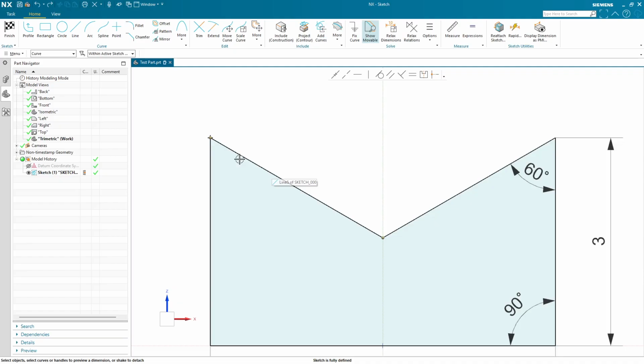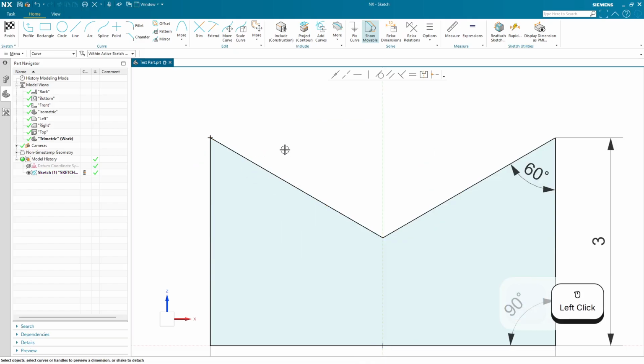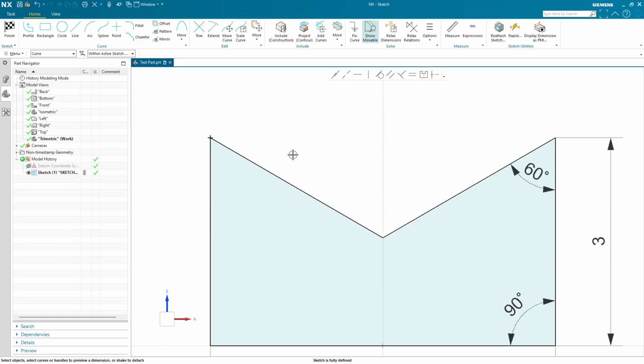So you might be asking, how do I deselect? You might have drawn stuff already or clicked on something and you're confused and maybe hitting escape to get out of there. To deselect things in NX, you hold shift, and as you hold shift, you click the thing that's selected and it deselects. If you've been fighting with it a little bit, welcome. That was your NX initiation. We've all done it at least once or twice. But yes, to deselect things in NX, bodies, lines, sketches, features, all kinds of stuff, you just shift, click, and it's undone.